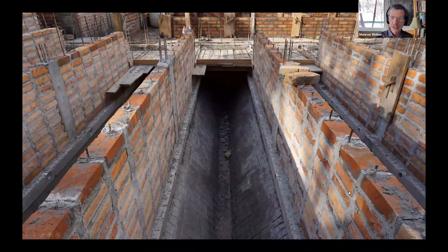The ledge that you see along the side here is a ledge that will eventually be used to help support the plate settlers. So the plate settlers will be sitting on that, on their edges, on the sides. This platform here is where there will eventually be our system of 4 channels that control the inflow and outflow into this system.